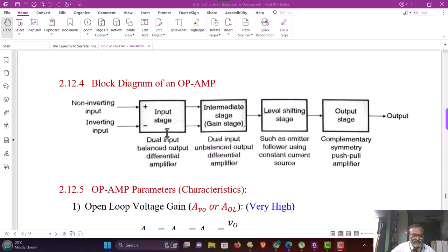Now since this amplifier cascading is done with direct coupling, the DC level or quiescent level of the previous stage gets amplified by the next stage, and therefore the quiescent level goes on shifting up, which effectively reduces the AC swing of the amplifier.